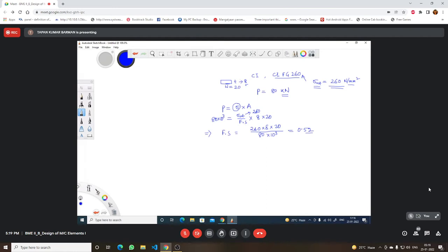I'm coming to your point. Now, why we are using here tensile strength? Why not yield strength? Probably your question was there. Why we are considering the maximum stress here? Since the material is brittle, this point is your tensile strength. This value is basically sigma ut. We need to consider that value only because we have to know this material aspect. This material is basically brittle material.